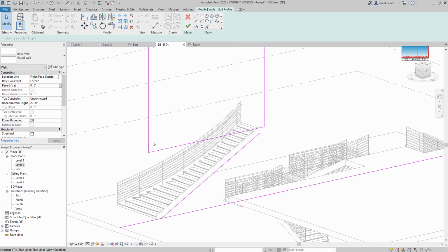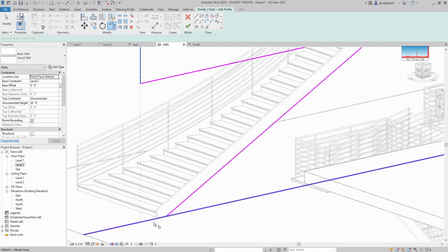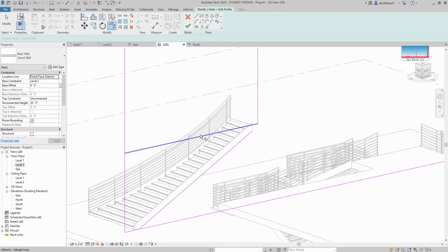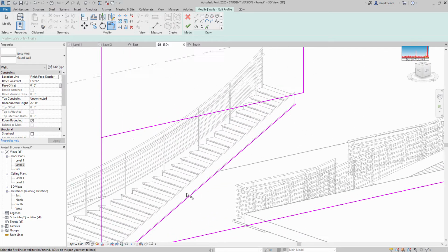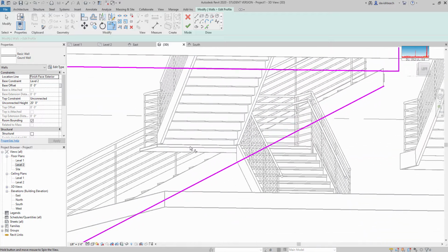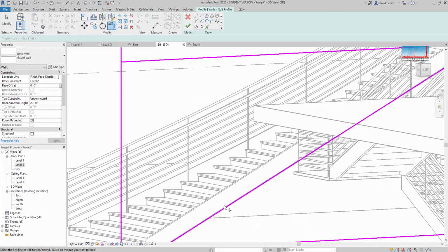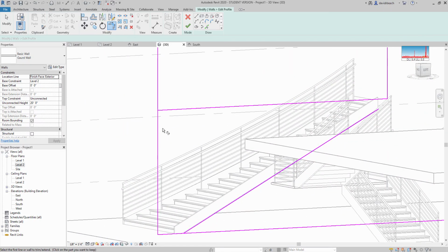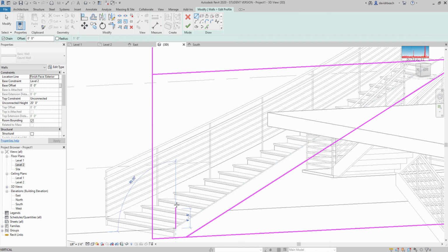Then I know that this was set at the right distance out from the last stair. I know that my height here to here, I need to be up from this height right here at least 42 inches.